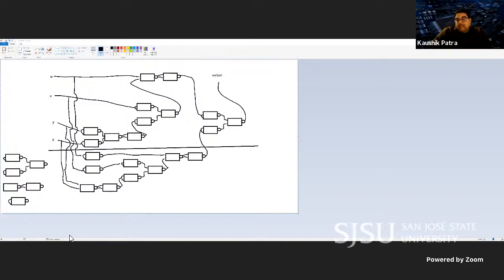Maybe another idea would be, when you come up with the expression, to convert it right there into the NAND only expression itself using the De Morgan theorem, De Morgan transformation, and then it would be an easier problem for you to draw the circuit. So make the expression first with the NAND only. Other than that, it seems okay. Your solution is good, wonderful. Thank you very much for sharing.